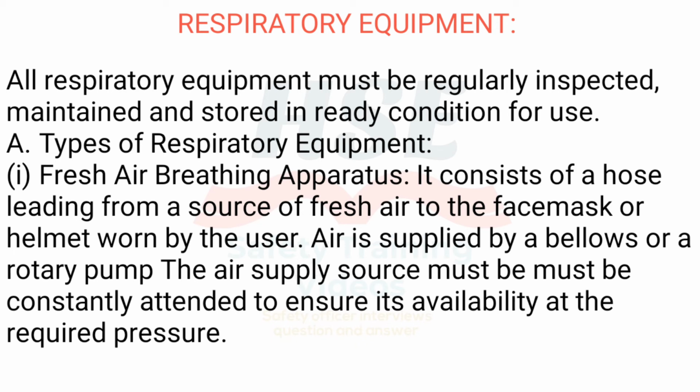It consists of a hose leading from a source of fresh air to the face mask or helmet worn by the user. Air is supplied by a bellows or a rotary pump. The air supply source must be constantly attended to ensure its availability at the required pressure.